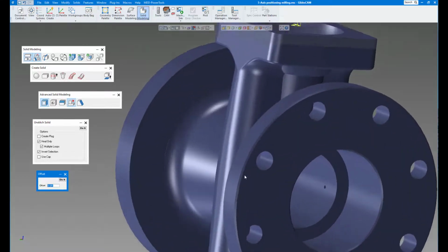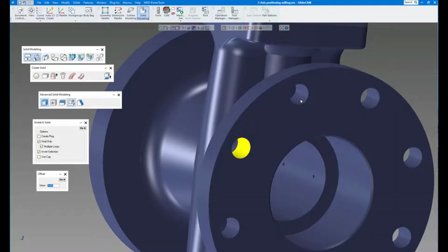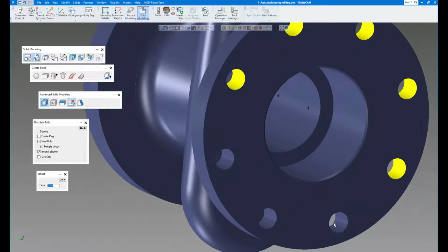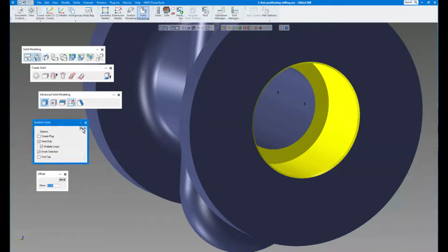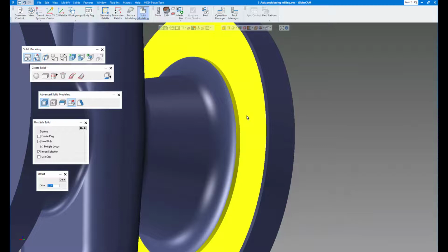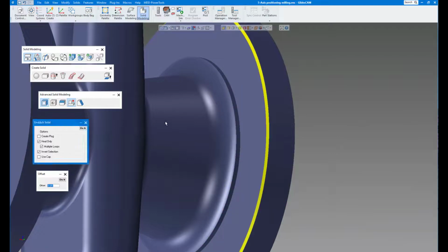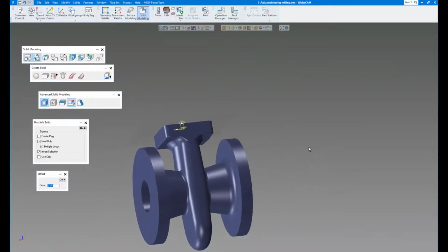So let's go to the other side here and let's heal up the chamfer, and let's heal up all the holes. All right, again, let's heal this, starting from the bottom. That looks pretty good. And we might have the same issue here on this side. Let's see. Oh, we got to get rid of the chamfer first. And let's try here and here and see if it's going to let us. Yeah, probably not, because probably the fillet overlaps that. So let's just select this surface and we'll add 1/8 of an inch to there as well. So now we have material there.